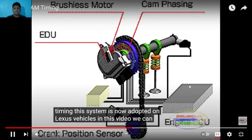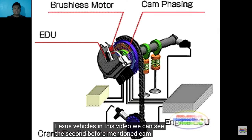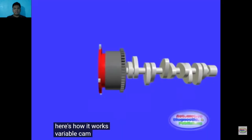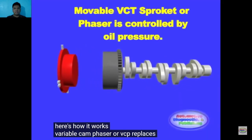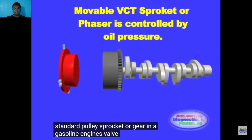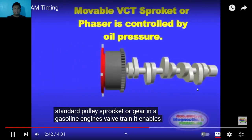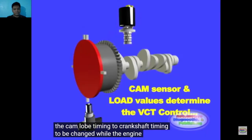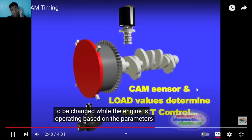In this video we can see the second, before mentioned, cam timing control system using oil pressure alone. Here's how it works. Variable cam phaser, or VCP, replaces the standard pulley, sprocket, or gear in a gasoline engine's valve train. It enables the cam lobe timing to crankshaft timing to be changed while the engine is operating, based on the parameters of the engine.